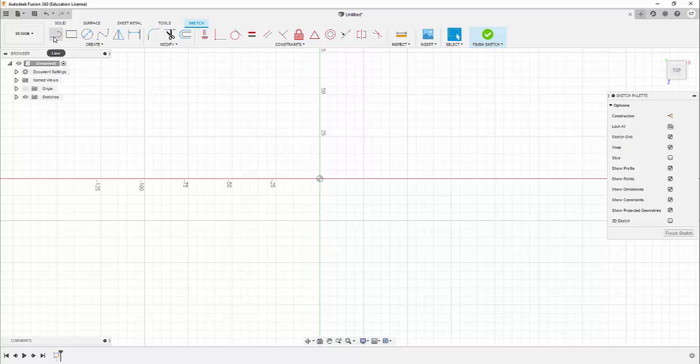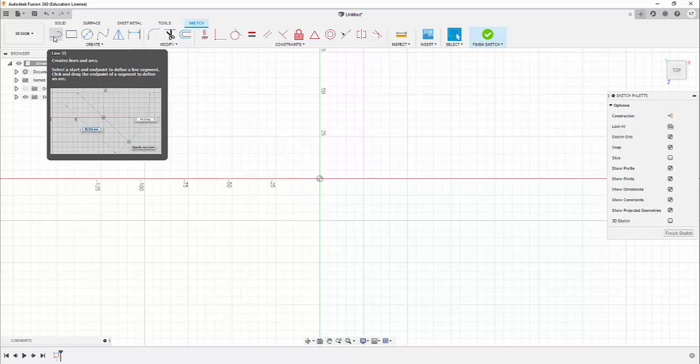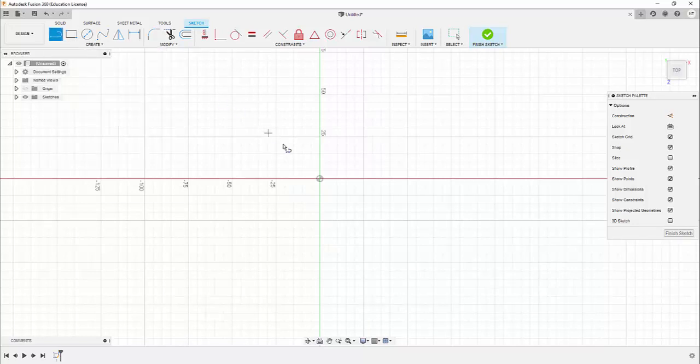The first feature I'll talk about is the line feature. The line feature simply can be used for drawing lines. Let's say I want to draw a line from this point to that point. I can use the line feature. I can also continue drawing my lines till I get some closure, or I can continue drawing my lines till I press the escape button, or I press on this mark over here to stop it. So that ends my line command.